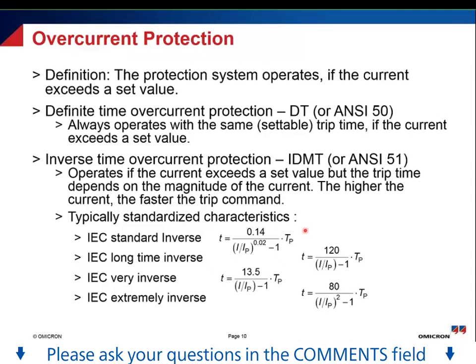Depending on where you are on this world, there are different standards. So, for example, the IEC standard is commonly used, let's say, all over Europe. But in contrast to that, there are other characteristics like the IEEE or the ANSI standard, which are a bit different to the IEC standard. And that also is shown in the formulas. So even if the characteristic is called very inverse, you still have to have a look at which standard is meant with this. So if it's the very inverse standard of the IEC standard, or maybe the very inverse characteristic of the ANSI standard.